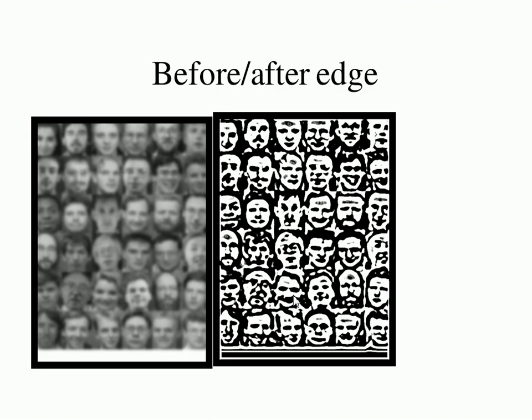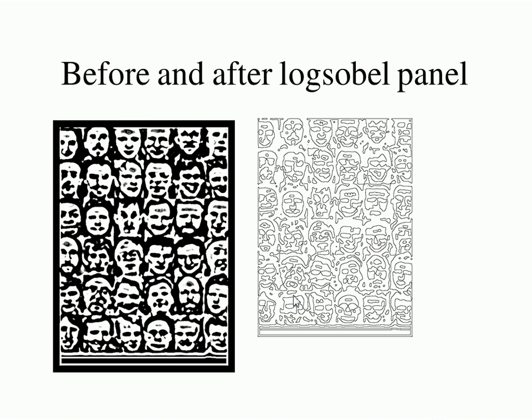Well, I could run them through an edge detector, right? So here's my little edge detector, and it's thresholded, and that looks like something. I could almost see taking that and making it into art. Etching it with my laser cutter, right? You can do that. But I wanted single pixel width edges. I don't want just these large areas because the laser cutter's got to have a place to go. So what I do is I run what's called a Sobel.